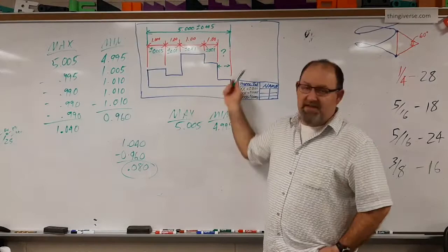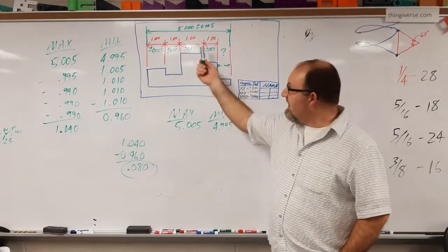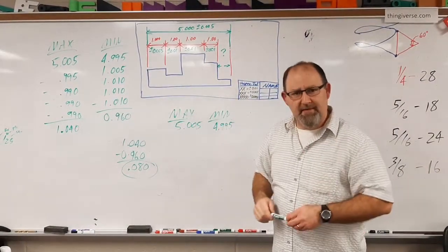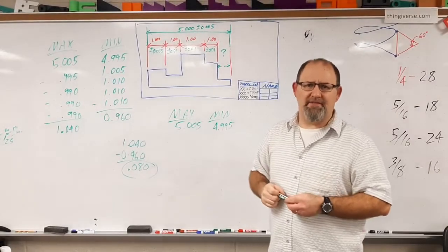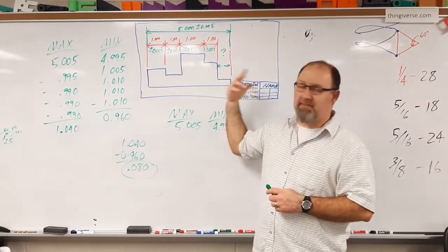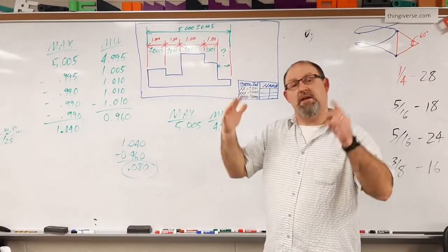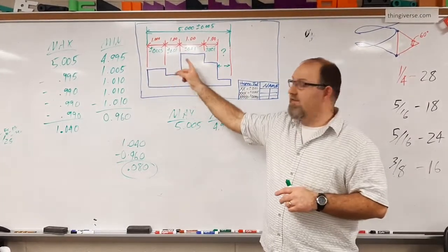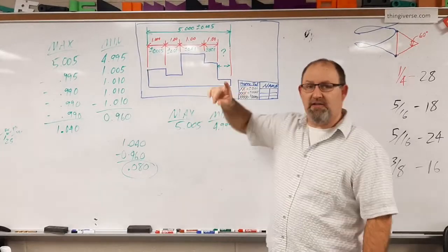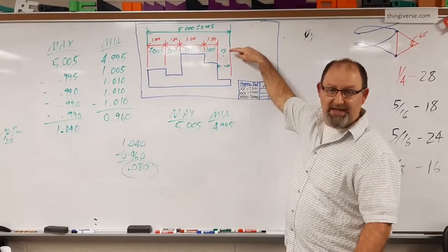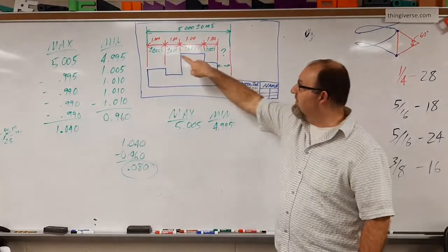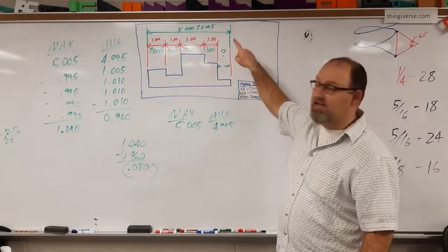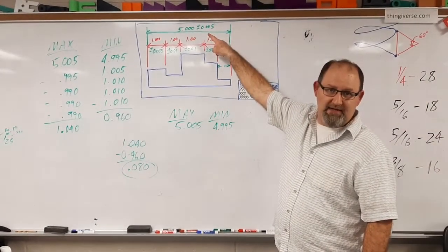So in this particular case, this is a common way. Typically, if you're in my lower level drafting and CAD courses, this is typically how we will design parts. So you know the overall length of it, and then you know the individual lengths. Remember, again, for machine or mechanical design, you never put all of your dimensions in here and put a guiding dimension up here.